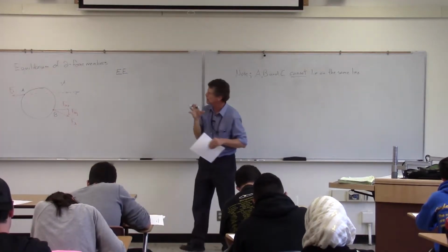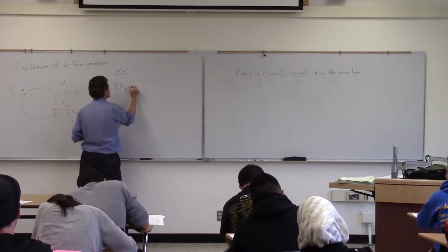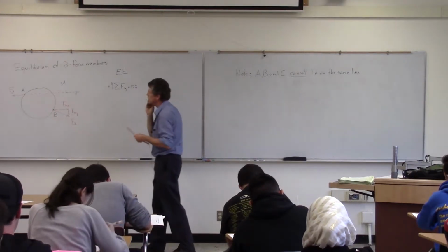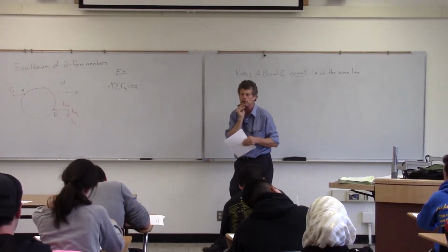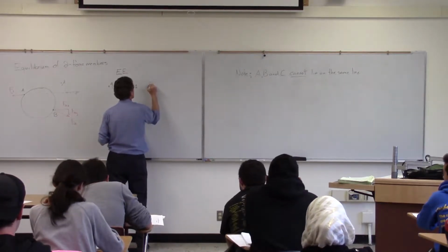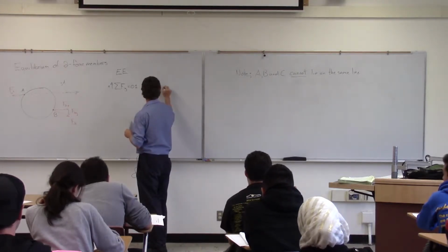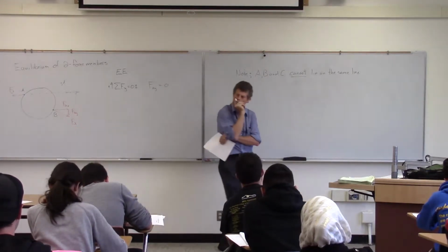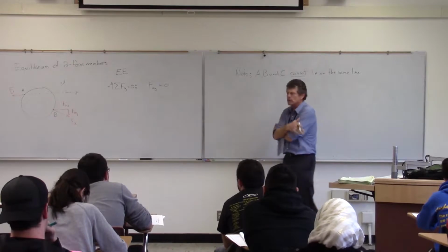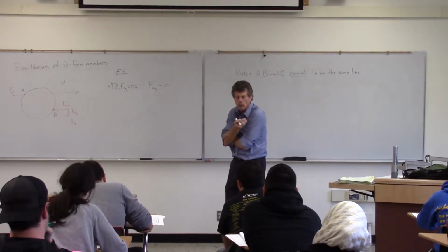And let's go through the equilibrium equations and see what they tell us. First of all, we'll start off with the sum of forces in the y direction. Okay, does F1 have a component in the y direction? No. Does F2 have a component in the y direction? Yes. Okay, so F2y, anything else? Okay, so the right hand of my equation says 0. Okay, so what that's saying now at this point is that my force 2 cannot have a y direction. It has to be parallel to the line of action of F1.